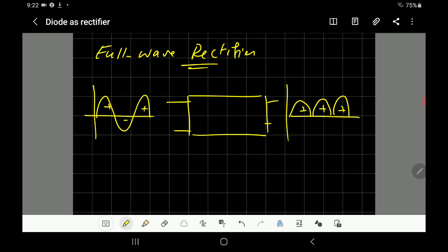So now we are in a better situation. If you do the integration as I proved for the first one, it will be the same. Remember that the average voltage of the half-wave rectifier was equal to Vm over pi. Now you have extra, so it will be double, because we were missing the half cycle in the first one.